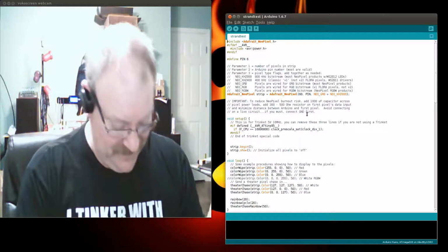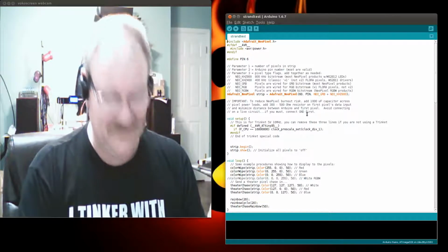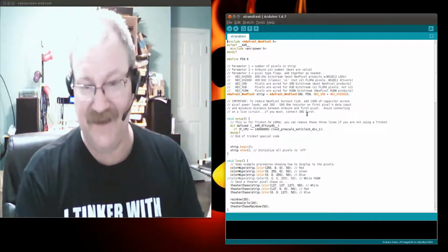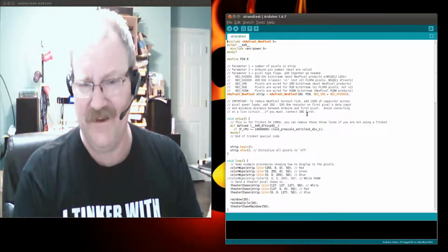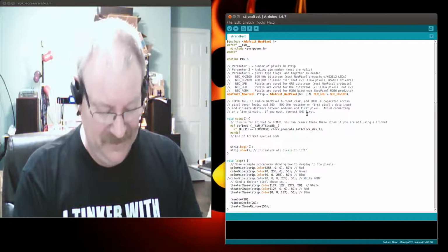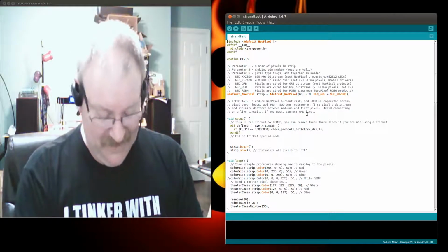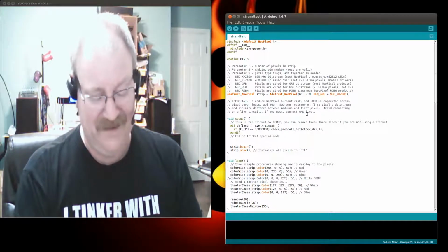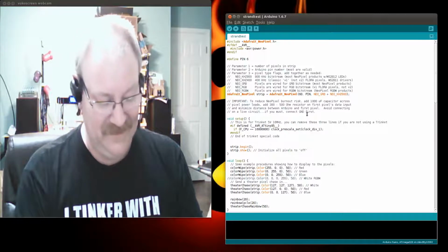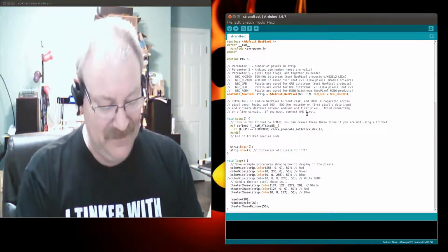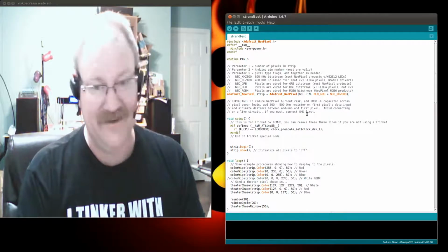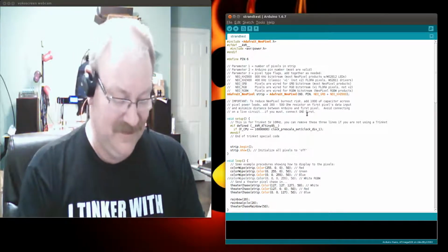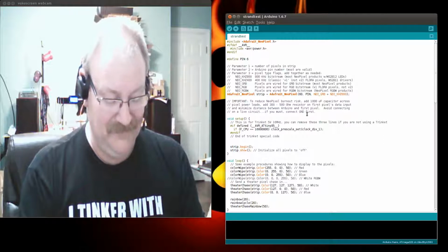So that's why it has so many capacitors dotted all over the board, to satisfy this requirement. For just testing the Neopixels for a short time, we're going to cheat. We're not even going to do it. Put the caps on if you want, but I've never had a bad result by not doing it, because the capacitance of the board and of the Arduino itself, and the way the voltage regulator on the Arduino works, usually handles the problem pretty well on its own.